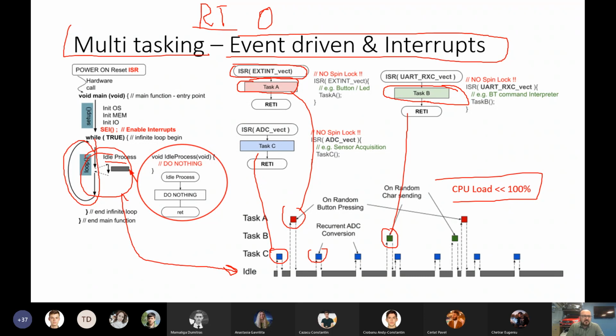Okay, started to have feedback. Thank you. Just define the proper interruption for every task. Because if a task is working with an analog interface, we need to set up the interrupt service routine for the ADC.